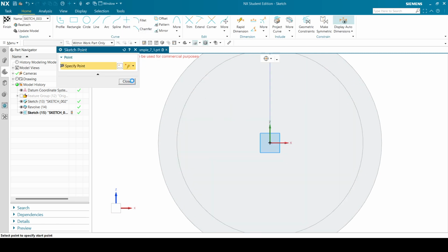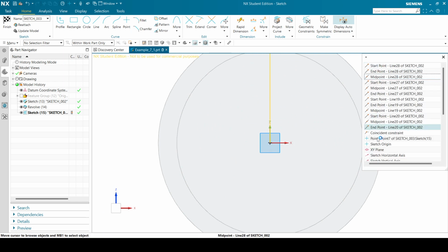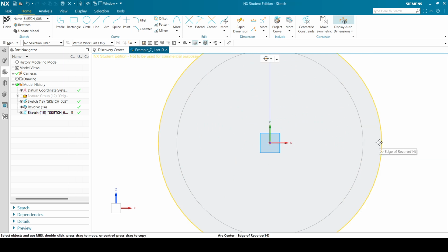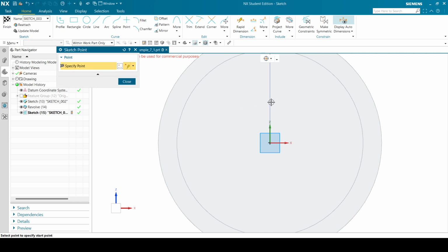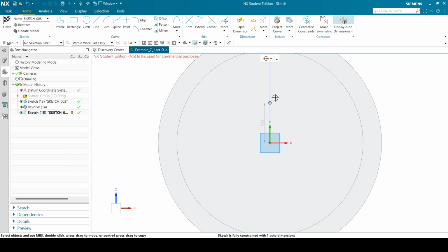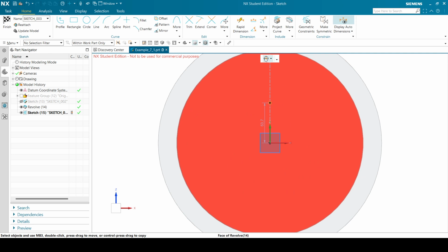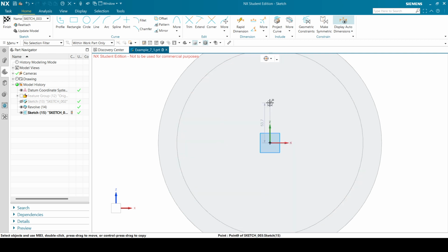Let's probably put it in the correct spot. Let's take this point, right click, just delete that, and actually add it at the correct position. So I put a point on curve constraint with that sketch. I'm just going to hide that sketch so that I can't accidentally select that. And I want it to be point on curve with the vertical axis.